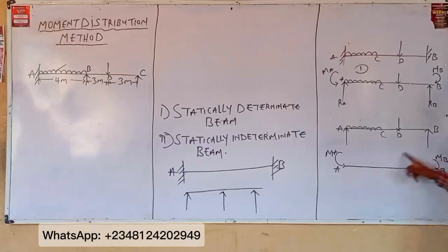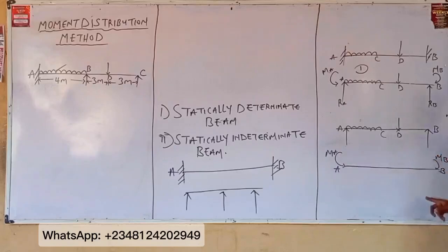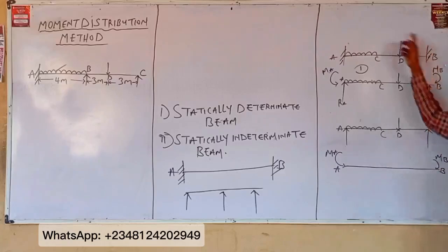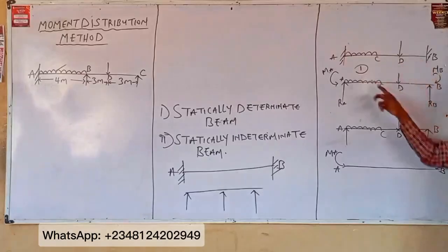You can relate this to the usual one that we know, the simply supported beam. For this simply supported beam, I'm going to draw my bending moment diagram. And for the moments at each end, I'm also going to draw my bending moment diagram. Then you bring these two bending moment diagrams together, and this will give you the bending moment diagram due to this fixed beam.